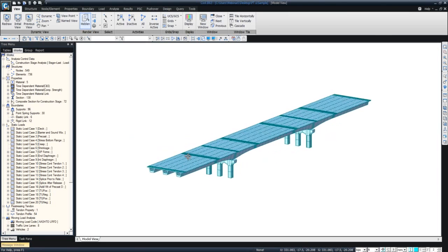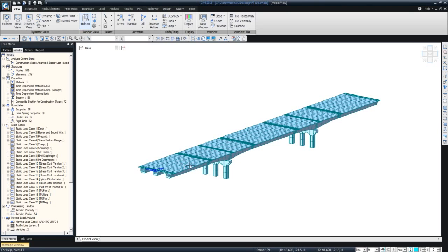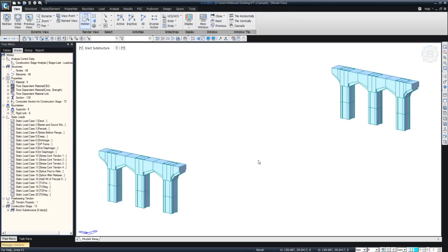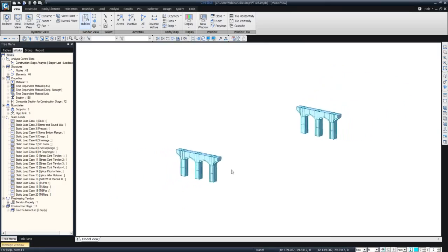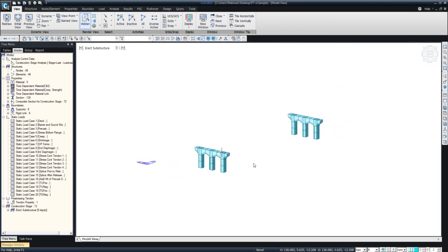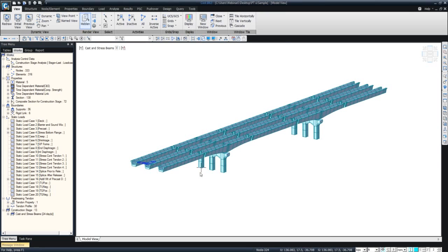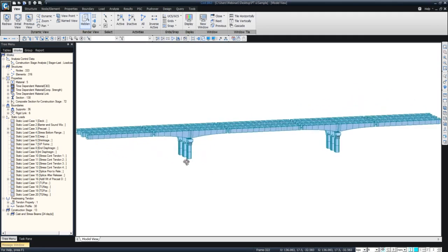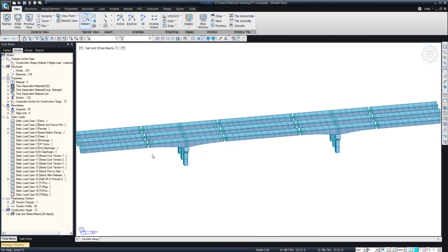Now this is how the project looks before it goes out into the field, and let's see different aspects of this particular bridge. The key essence for this type of splice girder project is its construction staging. So here we can see we have started with just the substructure. You can see the hammerhead piers here. Then we'll have the U-tub sections there without any cover, just the bare girders. And if you see right here, you can see the splice gap there.